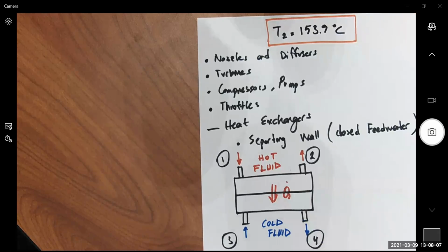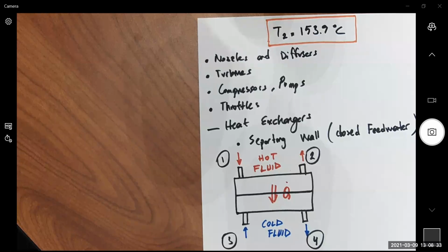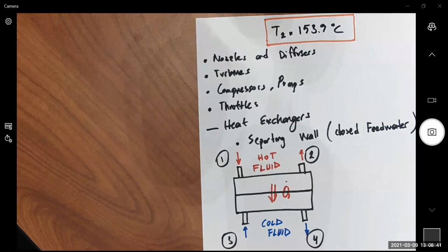Remember, when I determine my boundaries, I determine them to allow transient energies or mass to pass through. If they pass, I can keep track of them because I know what enters and leaves. If I put my boundaries around something and that property stays inside the control volume, I have no control over it because it never leaves my boundaries.